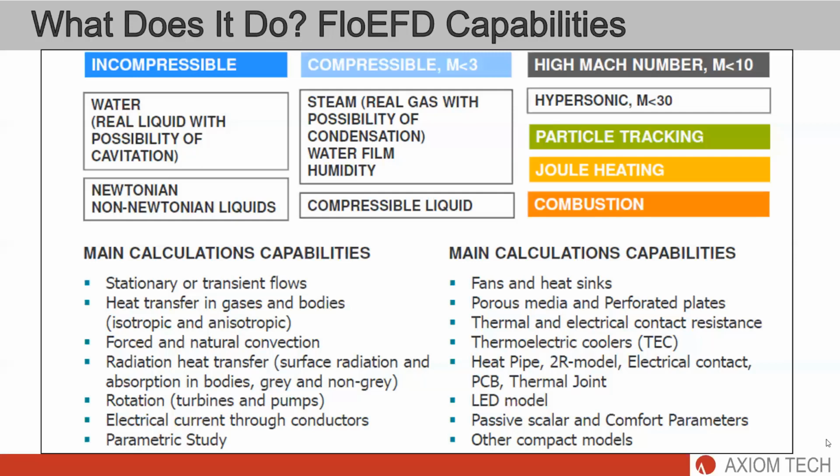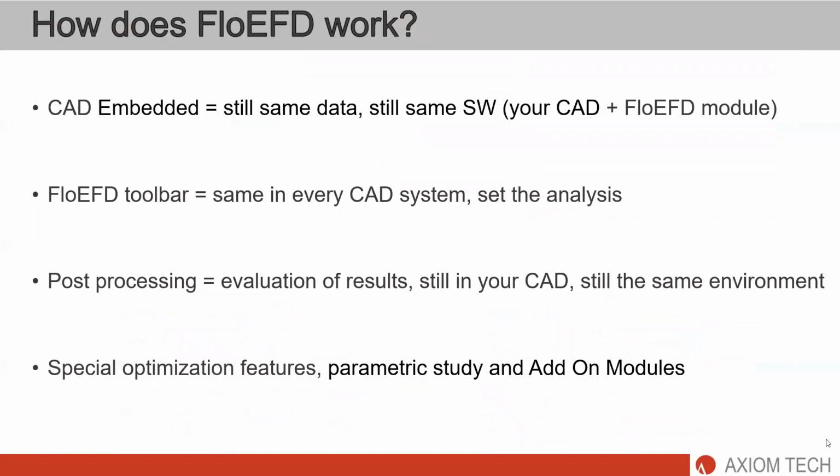Maybe on the next slide, I will explain how FloEFD works, or maybe some workflow. You have opened the assembly in your CAD, then you can save it as an idealized geometry, or you can work on the production assembly as well. You start and set up the analysis via FloEFD toolbars.